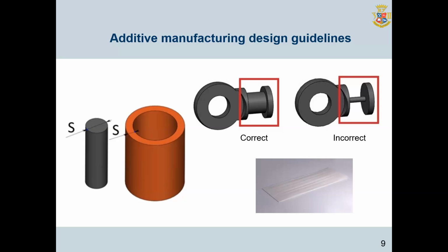Thus, the thickness of the walls and structural elements of the model must be sufficient to withstand certain loads within the framework of fulfilling the functional requirements assigned to the model. The geometric ratio of the parts of the model must correspond to the functional strengths and aesthetic purpose of the product. The use of large, thin, unsupported surfaces is not recommended due to the possible curvature of the surfaces during the manufacture of the model.